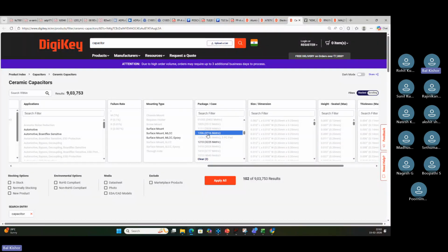Okay, so this is how it is better. For 10 microfarad, don't go ahead with 0603. The DC bias characteristic will be very bad with this one. DC bias characteristic, just now I showed you that with voltage applied, the value decreases drastically. So in these higher packages, that will be a little more stable compared to a lower package. Okay. So this is how it is.